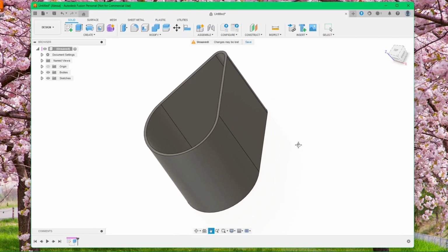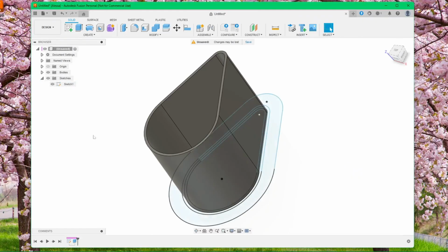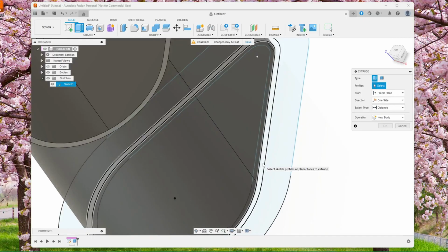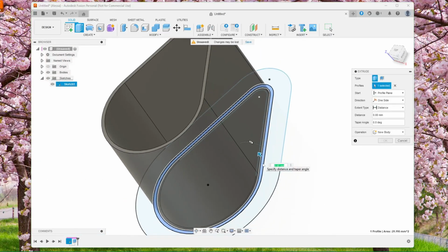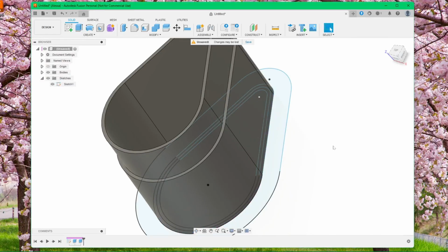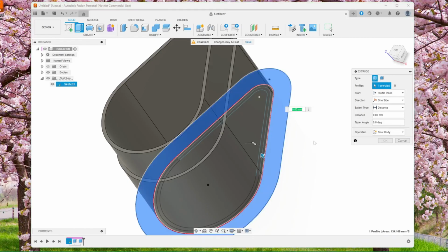After you created your first solid from a sketch, it will be hidden away. Go over here to Sketches, and click on this little eye. This will make it visible again. Click Extrude again. Select within these two lines and extrude this 10 millimeter. Enter. And then the last one, which will be our handle, here, and 3 millimeter.